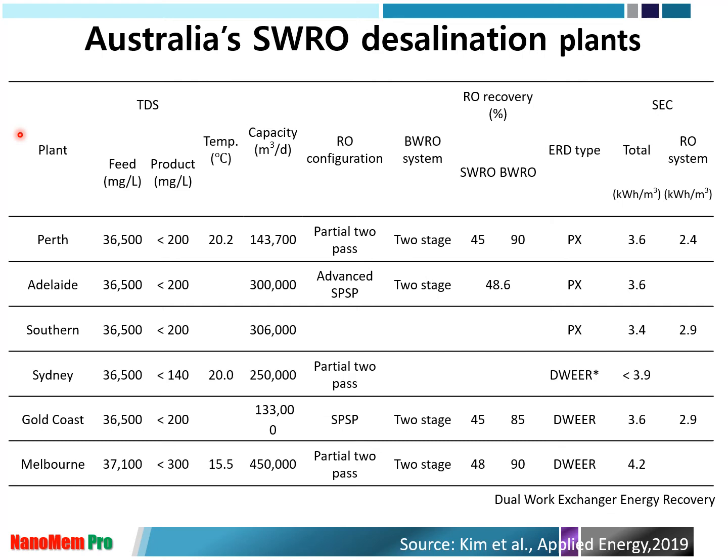That's the reason why they can make good water management, so that they shut down the desalination plant whenever they have enough rainfall. Also, when their dam level decreases, they can improve their desalination plant process and reoperate, and then produce the alternative water resource. So that's the way we have operated the SWRO desalination plant.